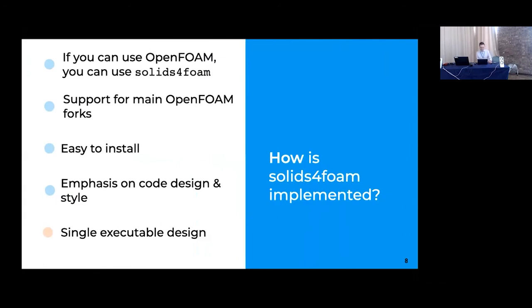How? So the idea is, if you can use OpenFOAM, then you can run an OpenFOAM case, you can run a Solids4Foam case. Things will be where you expect them to be. Boundary conditions and initial conditions will be in the 0 folder.